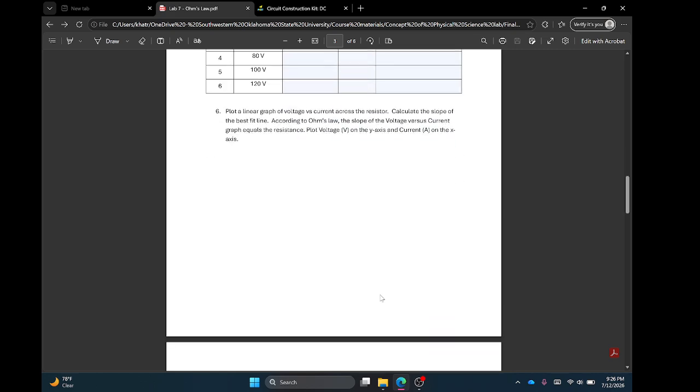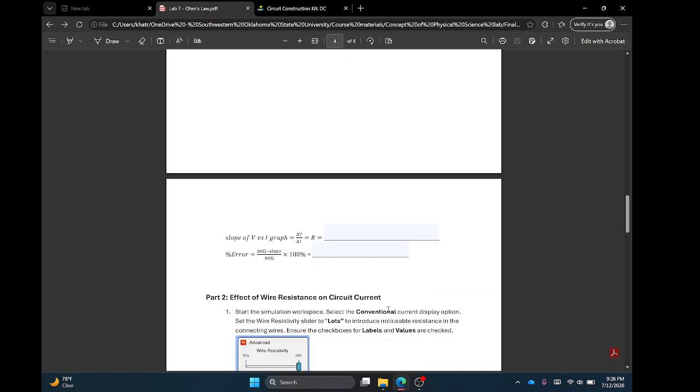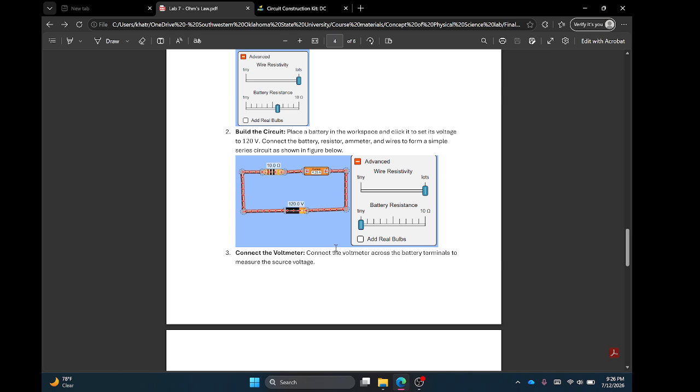For the second part, using the same principle, we will first calculate the overall resistance of the circuit, and using the total resistance and the known resistance of the resistor, we will calculate the resistance of the wires we are using in the circuit.